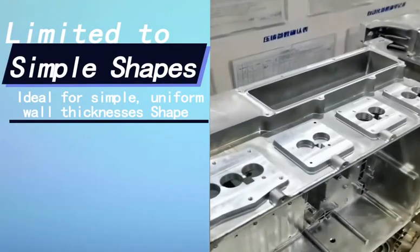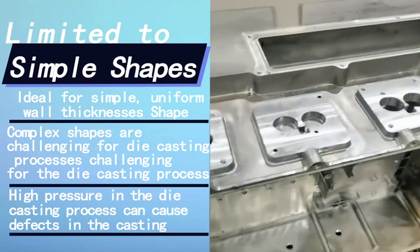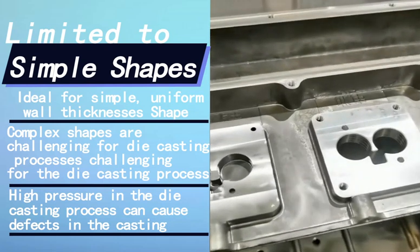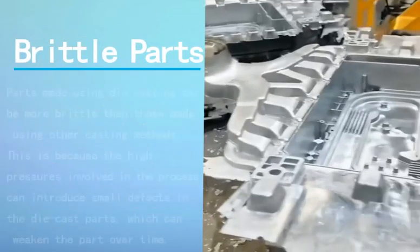Limited to simple shapes. Die casting is generally best suited for simple shapes with consistent wall thicknesses. Complex shapes can be challenging for the die casting process, as the high pressures involved in the process can cause defects in the casting.